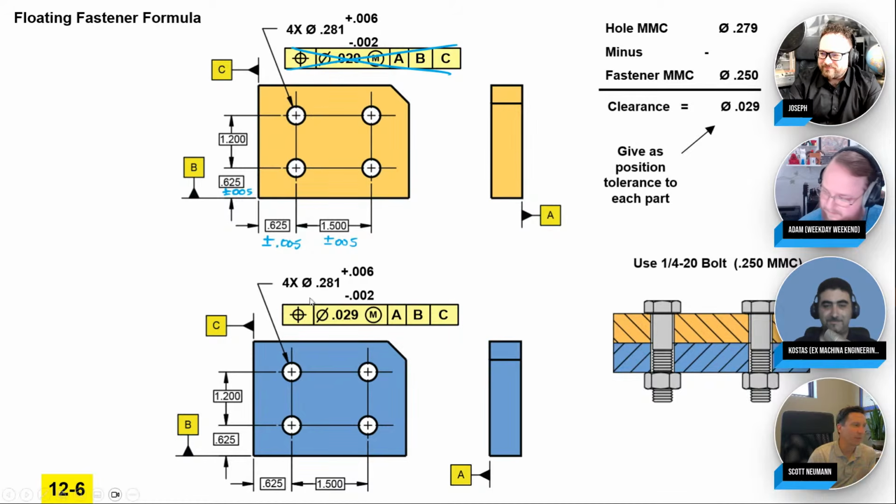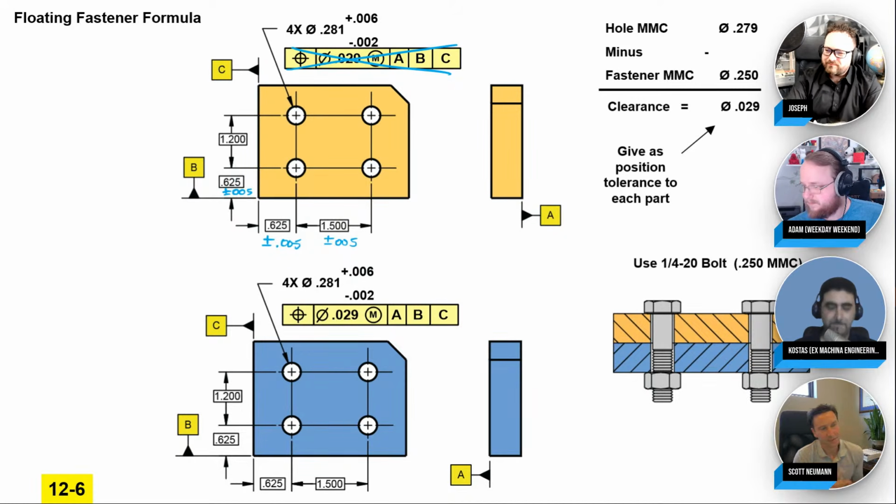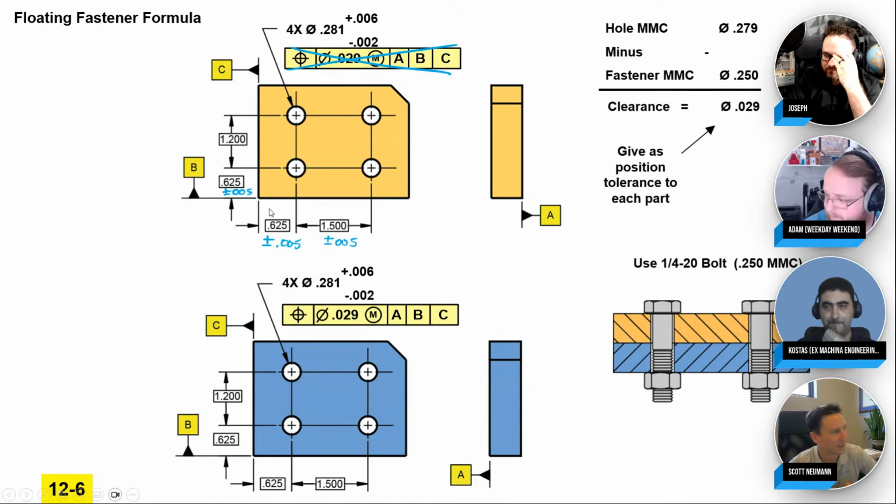Yeah, so it's really a far better system to allow maximum tolerance possible, but make sure it functions every time. Isn't that the 2 ultimate goals of a design engineer? Number 1, make sure it works every time. That's pure function. And number 2 is maximize manufacturing tolerance. Like Joseph said, it gives you 56% more. I'd even say more than that when you start thinking about all the stack up that can occur. So yeah, use position tolerance, way, way better.